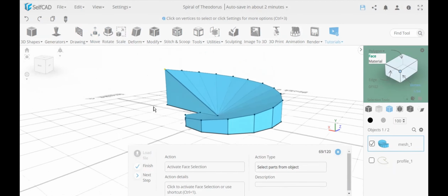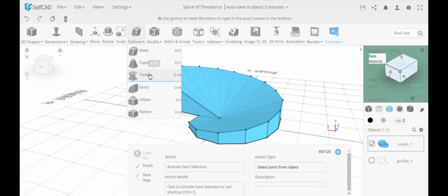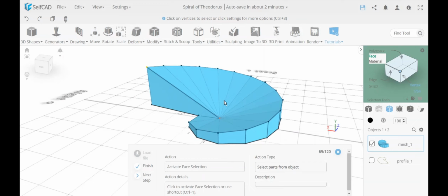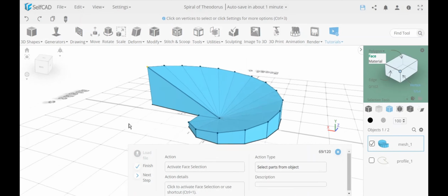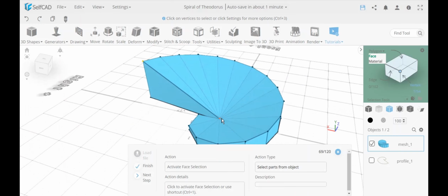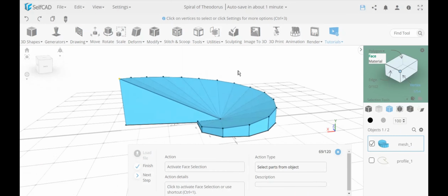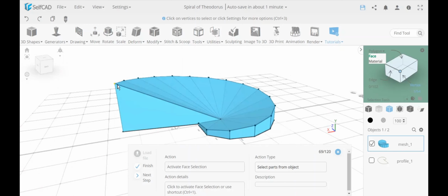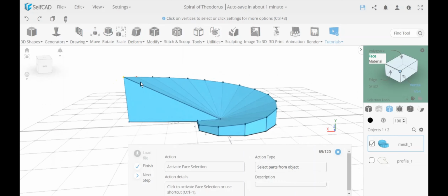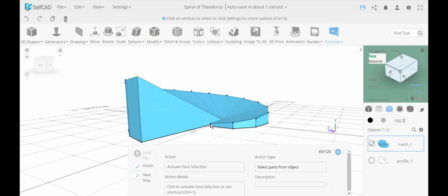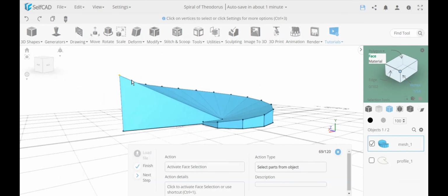Now I actually tested, you can do the same thing using the inflate tool. If you use the inflate tool, it will usually inflate from a center pivot, so it will not be as accurate, but the inflate tool has an option to set the origin. So if I set the inflate tool origin to the origin from the center vertex, it's actually going to do the same thing. The starting point is the same and the finish point is the same, but it's not 100% accurate following like this. And now that we did the manual method, we know it's 100% accurate, that each one is exactly 5 higher than the other one. The height over here is 5, this is 10, this is 15, this is 20, and so on and so forth until the end.